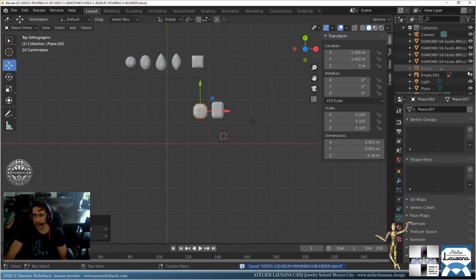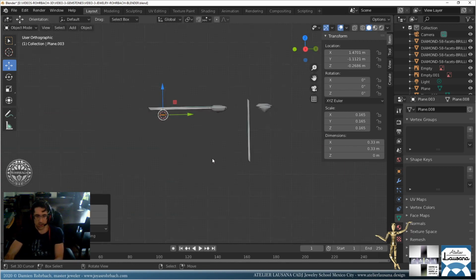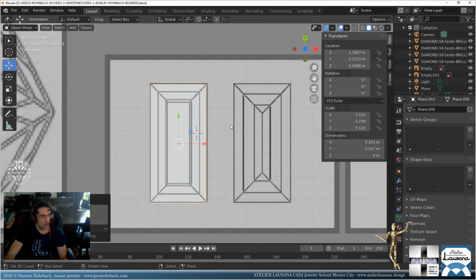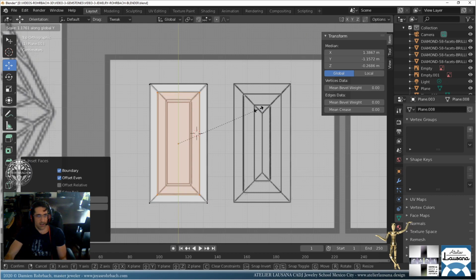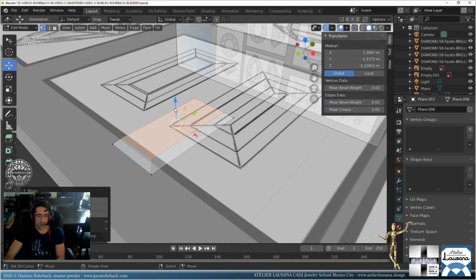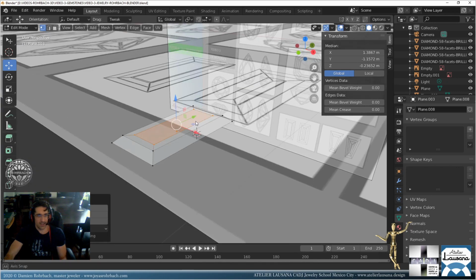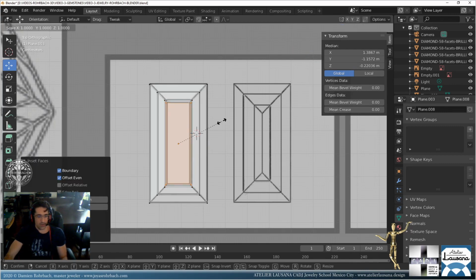A nice set of stones. We just have a very simple stone that is very useful in this one, which is the baguette. Let's add a mesh right there. It's the same process. So like I said, once I explain the process, it's always the same process. So you can create any type of gemstone. Okay, let's go here. Let's do a Y, SY. Let's already move it up. And you can go faster, obviously. Y, SY, Y, SY.